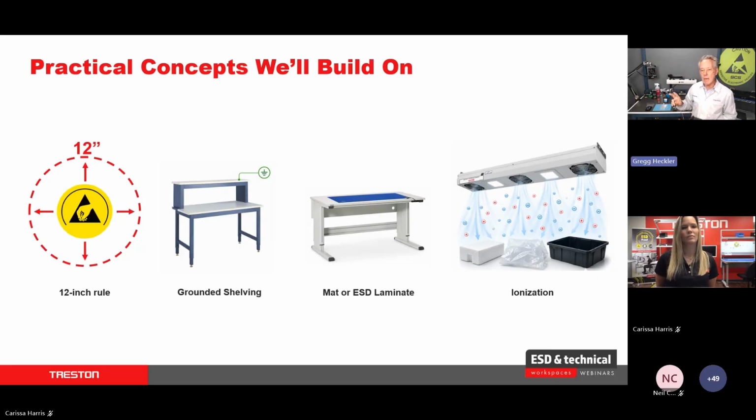And so maybe you're clipping those on the back of the shelf. There are two things to understand about packaging. One is that it should at least be dissipative and/or conductive, but two, all conductors need to be grounded, whether it's the IC on the component, whether it's the hand tool when I'm holding it, whatever it is. When I clip this on, this needs to be conductive. Otherwise, it's an isolated conductor like that metal paddle. So that's something to keep in mind. It's also important that we have a properly grounded ESD work surface. If I set this tote box in here full of boards, now I'm grounding that tote box, and consequently, anything touching that, components, they're grounded as well.